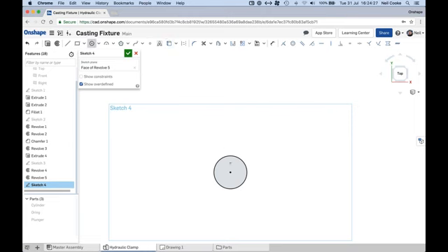Okay, when you are sketching, what you'll find is that you create a circle, for example, and you get the option, you can see that there's a value there highlighted. You get the option there to actually type in a value. So just typing on the keyboard will enter that value, add the dimension, and turn it black. So the difference here, obviously, Creo will give you those dimensions automatically, and also make them, and then you can convert them to regular ones, or you can override them with existing dimensions.